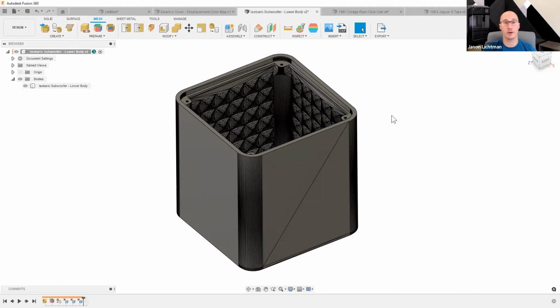The key though for now is that if you would like to convert to solid and that's all you care about, you can very much do that in Fusion 360, even if your particular mesh is more than 50,000 triangles. Keep in mind though that the more triangles or polygons you have, the harder it is going to be on your system. So unless you have a super awesome workstation, be wary of trying to convert a 2 million polygon mesh, as that would be pretty rough on your computer, right? Can it be done? Absolutely, but it is going to reduce your performance.